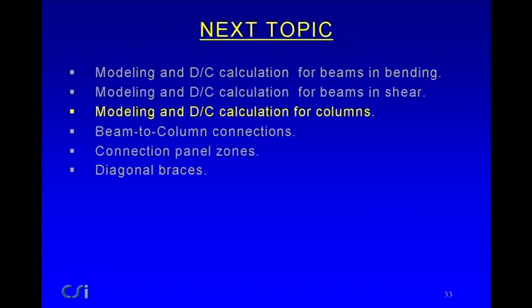You could do it by assuming the worst case, and you could specify a shear strength reduced by the worst hinge rotation you might expect, but this is a little more sophisticated. It will actually include the hinge rotation effect for you.